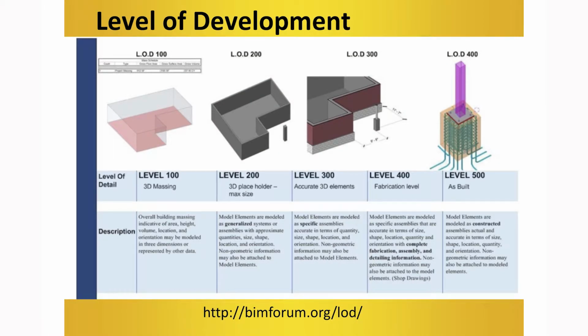That's what I call little BIM, just model coordination. That's low hanging fruit. If you're modeling and other people are modeling, you should be looking at your models together and solving those issues before you're in the field. Obviously, there's also visualization, the 3D aspect of being able to look in a room and cut a plane for everyone to better understand, because some people just can't visualize 3D information. You guys all can, you're experts, but some things can get misinterpreted.